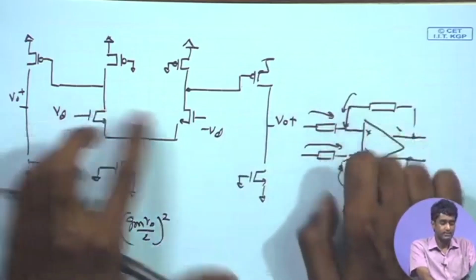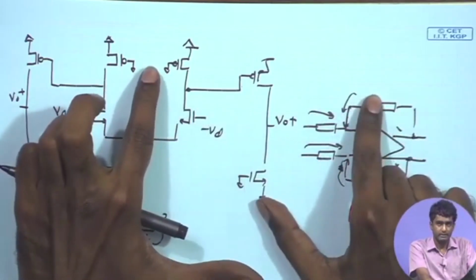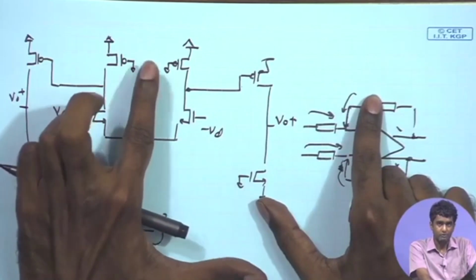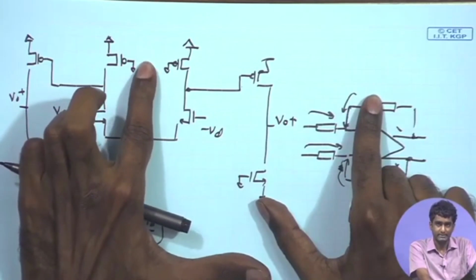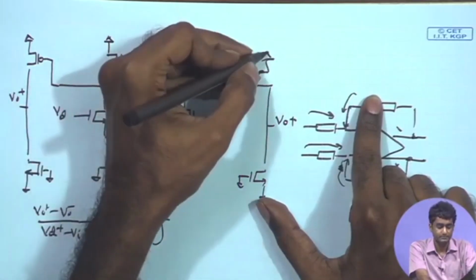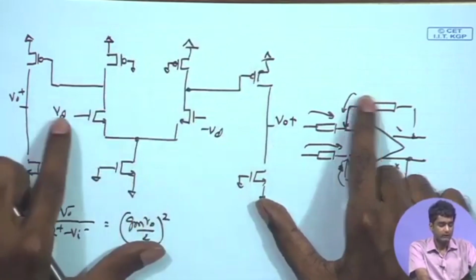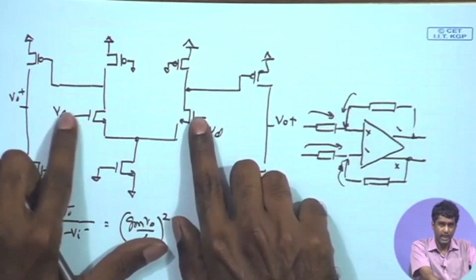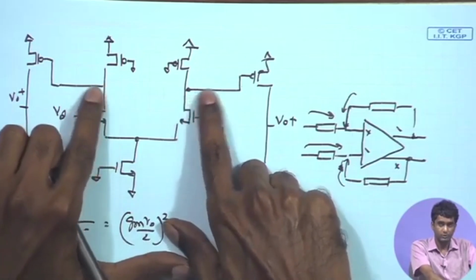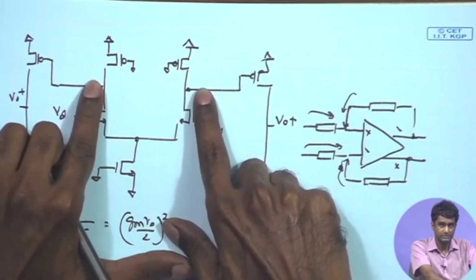As a result, we are assuming that the voltage provided over here by the common mode error amplifier is almost constant. It is just a DC bias, and therefore we are putting an AC ground over here in the AC equivalent circuit. Even if there is a significant common mode at the input, the differential amplifier also ensures that the common mode at the output is sufficiently small.